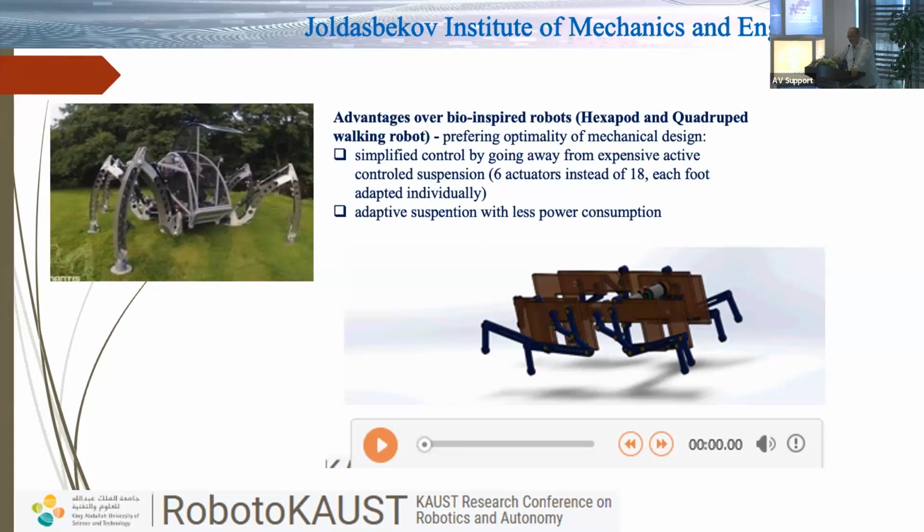And on the other hand, if you calculate from the point of view of the theory of machines and mechanisms the number of degrees of freedom of such a system, like a hexapod, like a robot, you will have an over-constrained system, because the number of degrees of freedom is much less than the number of actuated joints, actuated motors. Therefore, we have a statically undefined system, which is not possible from a theoretical point of view.